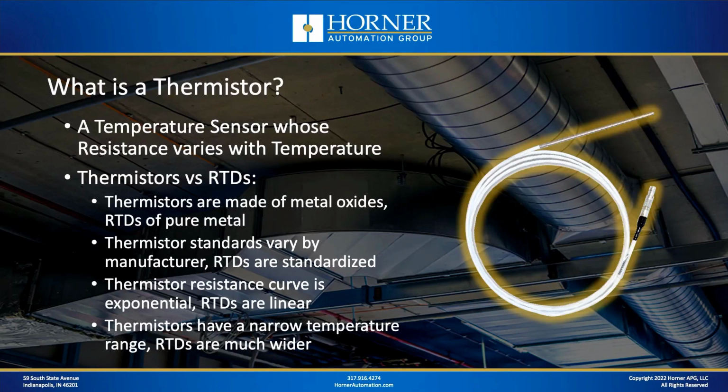What is a thermistor? Well, the basics are it's a temperature sensor whose resistance varies with temperature. But wait a minute, that's also the definition of an RTD as well. So let's compare and contrast thermistors and RTDs, the similarities, but primarily the differences. Thermistors are made of metal oxides or combinations of metals, whereas RTDs are most typically pure metals.